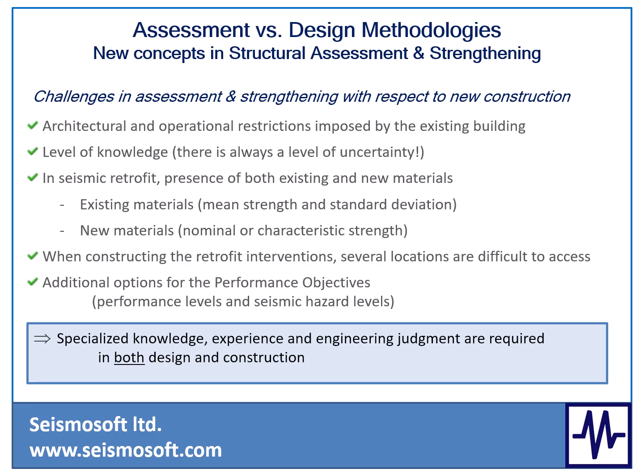Furthermore, the challenges imposed to engineers in structural assessment and retrofit with respect to new construction will be presented, and it will be explained why the entire process is more complicated and difficult, due to the architectural and operational restrictions imposed by the existing building. The new concepts, like the knowledge level and the confidence or knowledge factors, will be described, and it will be explained how to treat both new and existing materials in the same model.